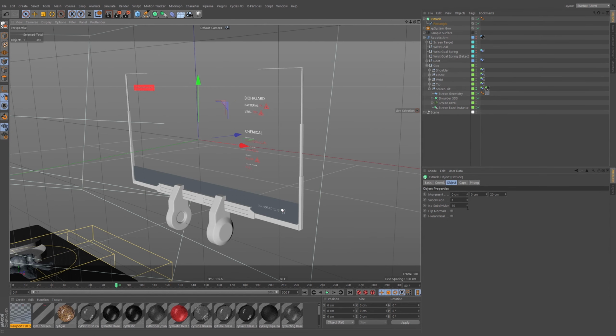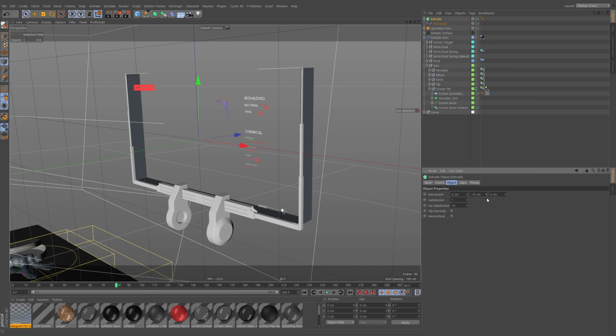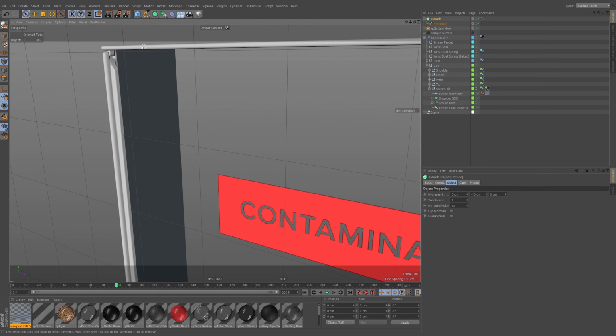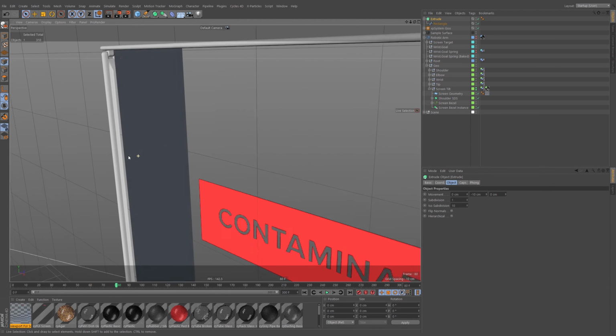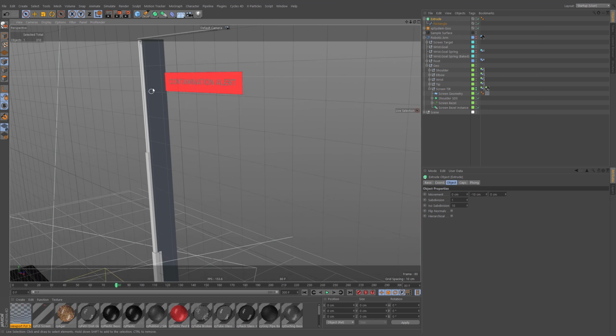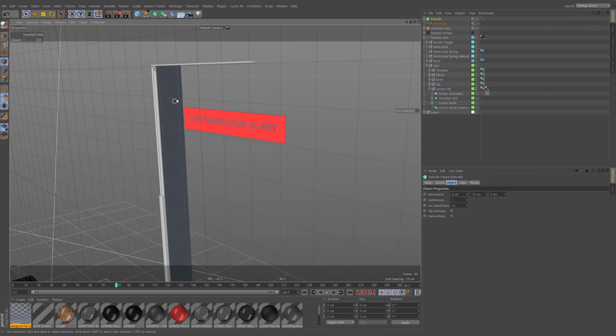And you can see now we're actually extruding 20 units on what is Z in our world space. I want it to move on the Y in our world space, so that's going to be the second one along. I'm going to exaggerate it to start with. I'm just going to do 10, but this is actually going to be very thin. The reason I'm creating this piece of geometry is I'm going to emit the particles from it, and I want them to have the direction of the polygons. So it'll all make sense in a second when I add an emitter.